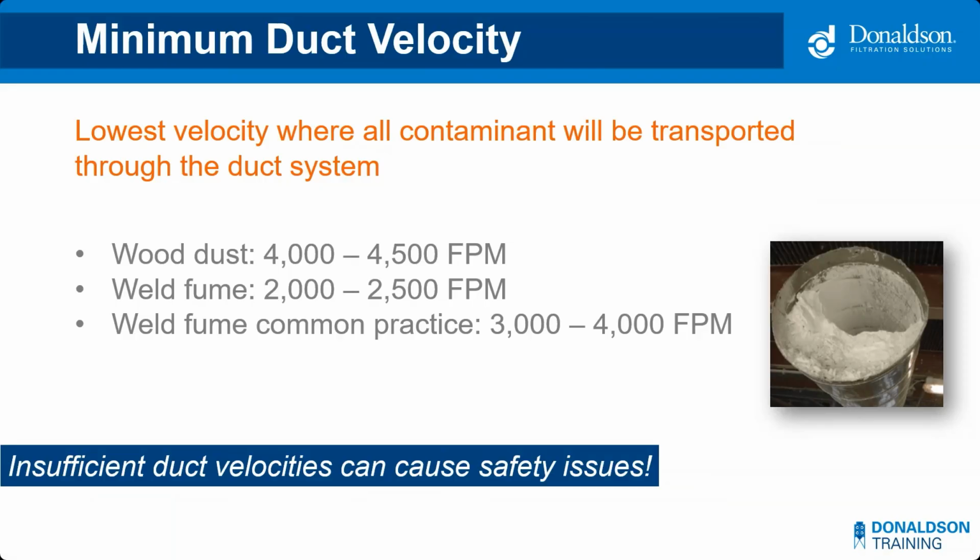If the duct velocity is too low, dust could settle out within the duct and cause problems, such as safety issues. Now, let's imagine the dust collecting in the ductwork, like in the image, getting too heavy, and the ductwork falls and can ultimately lead to a total system failure and hurt individuals. If the duct velocity is too high, it won't create any safety concerns, but it will require more energy to move the air through the duct. Ultimately, this could impact the size of the fan as well and create issues such as increased noise, abrasion, or wear and tear. So again, a critical design factor.